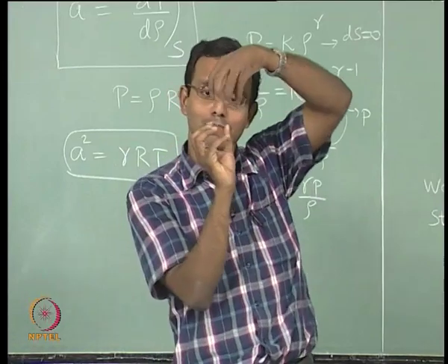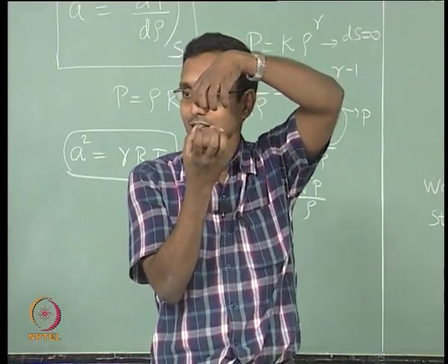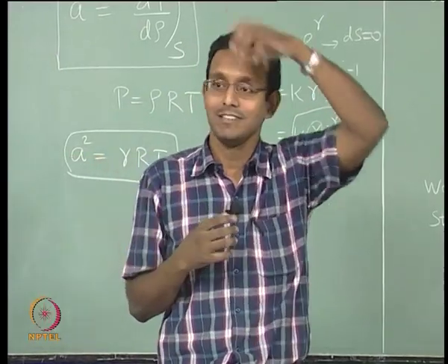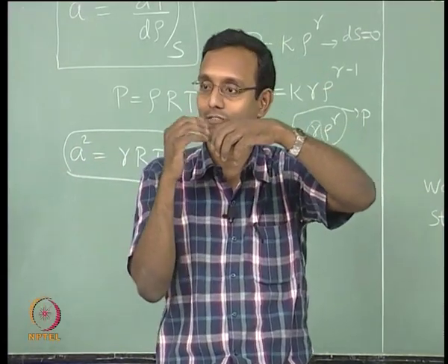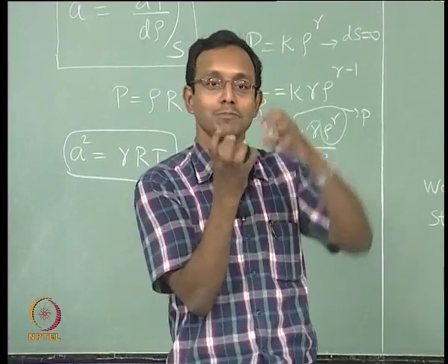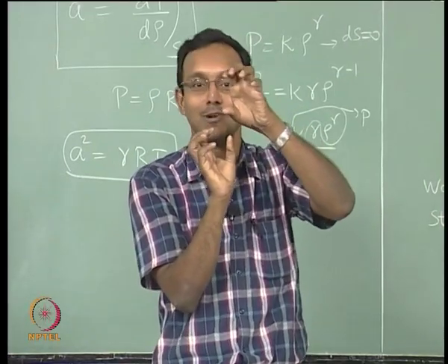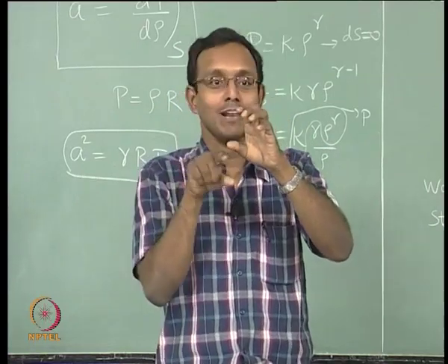If the top fluid element is colliding less compared to this one, then we know that there are fewer molecules present on the top, which actually means what? There is low pressure there, high pressure here. Now there will be a wave of information travelling. Why? These molecules find that it is more difficult to sit in this volume, it is easier to go sit in the top volume, so they will go up there, and so this fluid element gets empty.